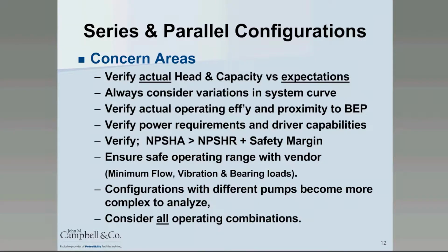You also want to verify your operating point. As you start to move further and further away from the operating point, then minimum flow conditions on the left-hand side of the chart, or concern towards vibration and bearing loads and seal damage, if you're seeing those things, you might want to go back, look at your operating point on the pump curve, and then talk to your pump vendor about the suitability of that operating point.